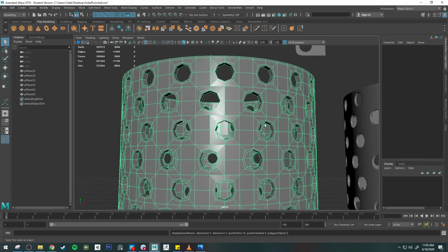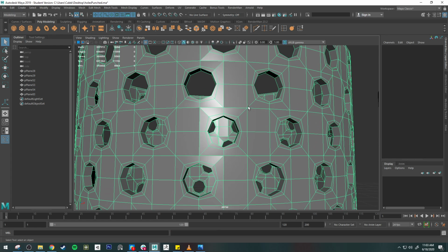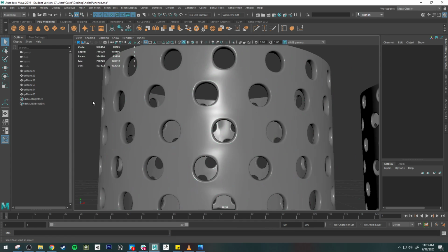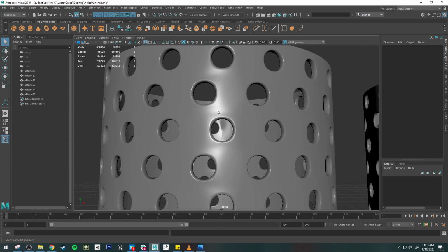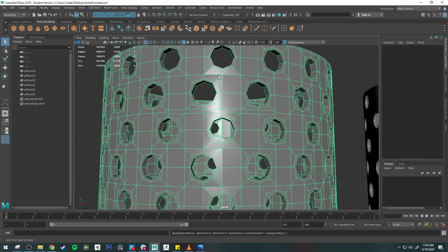This one, these edges are pretty straight, which is nice, but those poles are causing a lot of pooling, right? There's this really intense pull. They don't have any spacing between them. I could add a space to it. I can maybe select this. It won't let me select all these edges, but let's say I'm just going to put a bevel here. So I can put a spacing in there, but the problem I'm going to run into is now I'm going to get a kind of divot right there, because these faces are no longer evenly spaced. These two are the same size, but this one's really crunched, and so it's starting to compress a lot.